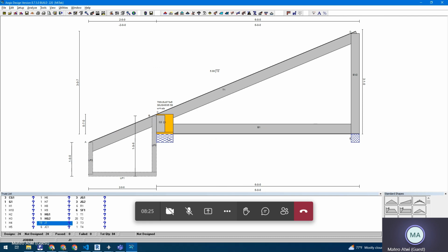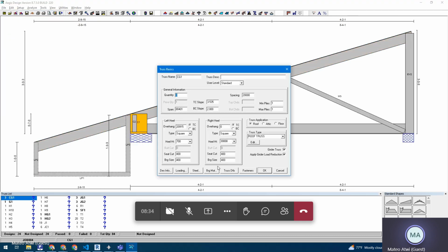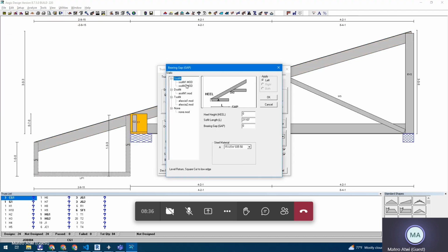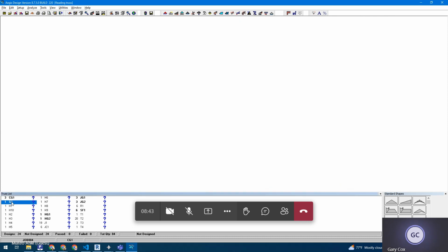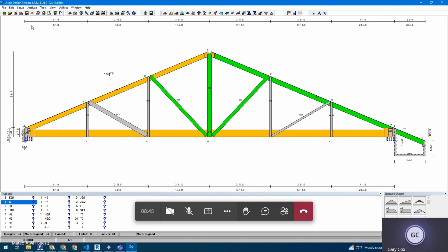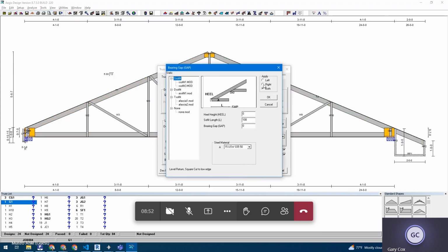But you can go in and fix that, go to the details on that truss and say, I only want it on one end. You could fix it. Okay. So I would do edit basics, truss details, and I would say on the... Right now it just says left, but you'd have to say both if you want it on both. That one made it only apply to the left. Yeah. On this one, you'd want to go... Yeah, I had the wrong truss basics. And then change it to right only, because you only want it on the right side.